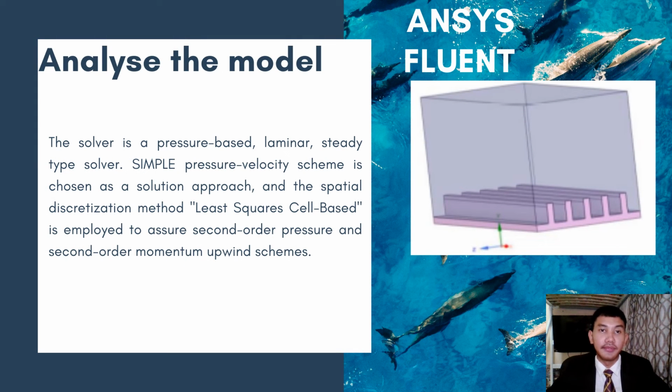The setup that will be done in ANSYS is pressure-based for the solver, laminar flow, a steady type solver, the SIMPLE pressure-velocity scheme is chosen for the solution approach, and the spatial discretization method QUICK-based is employed to assure second order pressure and second order momentum upwind schemes.